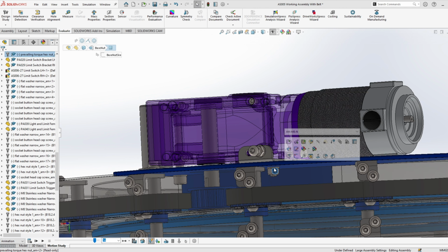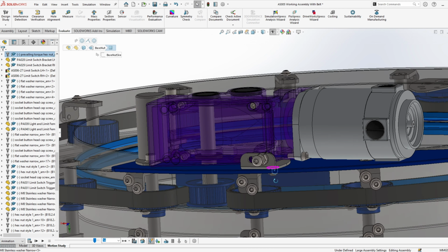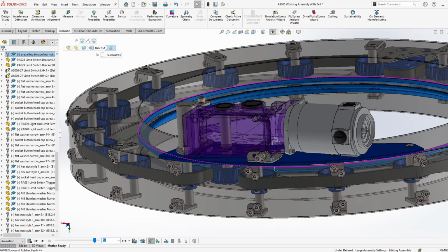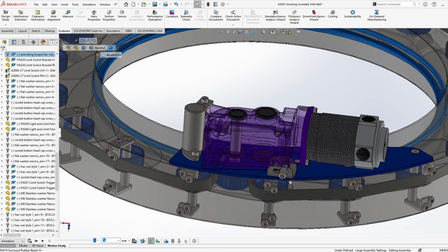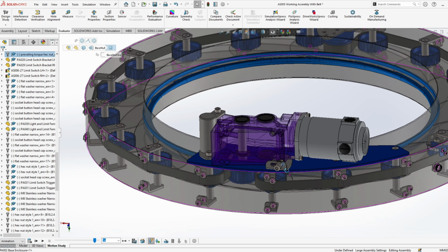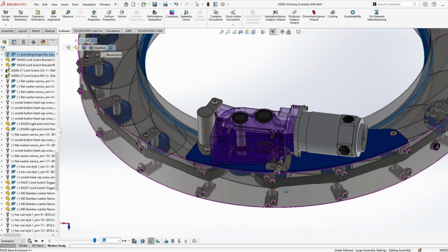There's the lock nut and the washer sits above it. So it's important that this countersunk bolt is not overly tightened as the mounting point lets the bracket pivot and glide on the anodized platform, allowing the gearbox motor to float and to be fastened in place.